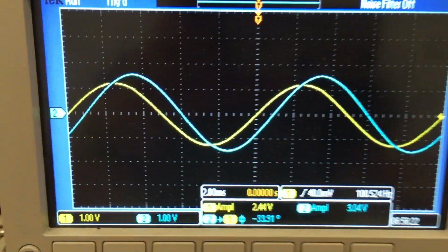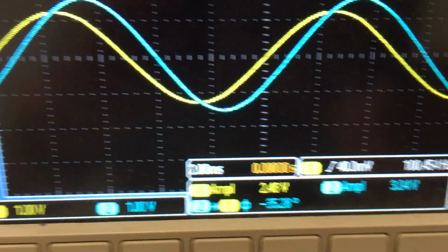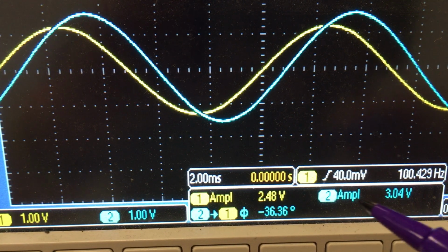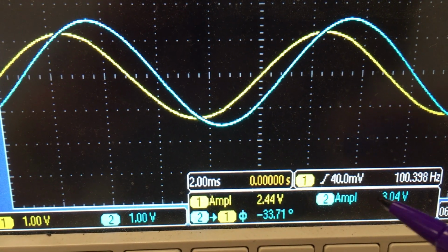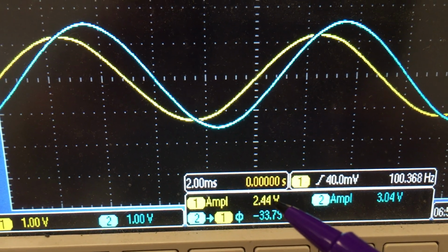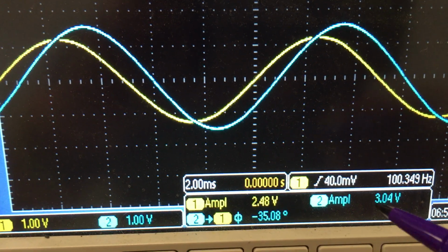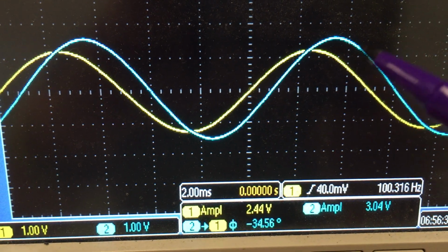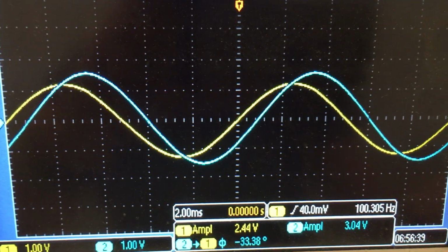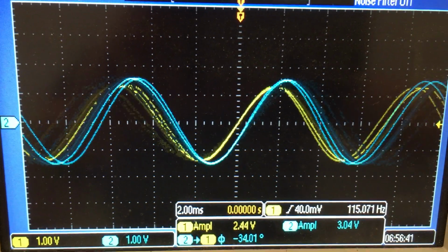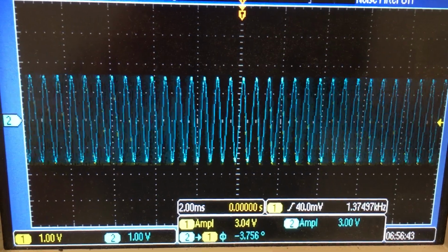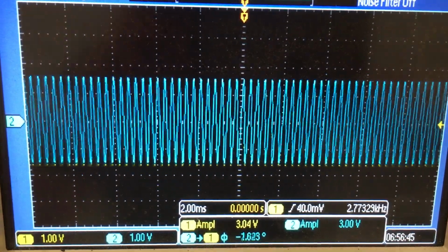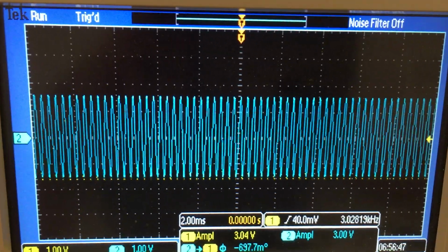And we see that the effective resistance of the capacitor has gone back up, right? Not all of the voltage is dropped by the resistor, just a majority of it. But pretty clearly the height of one signal relative to the other has changed. If we go up in frequency again, go way up to, I don't know, 3 kilohertz.